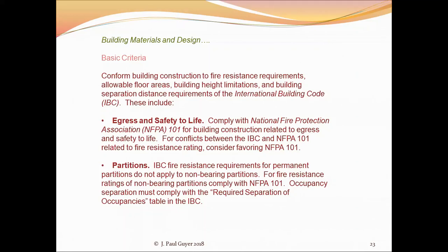And the fire resistivity of the construction of barriers, the walls, floors, is very important with regard to the egress routes, the corridors and the stairwells, because for life safety purposes, you want those features of a building to maintain their integrity for as long as practicable, to allow the people as much time as possible to get out of the building.